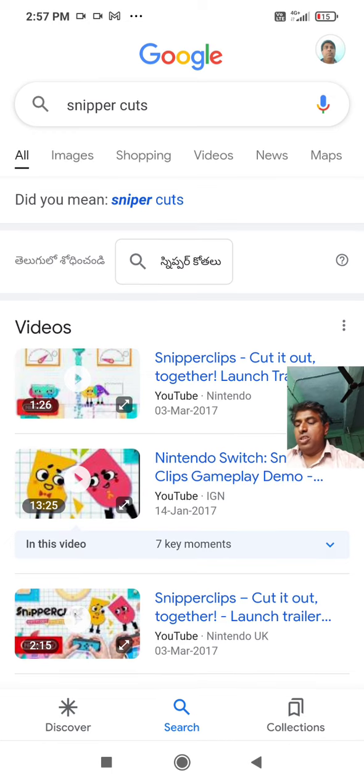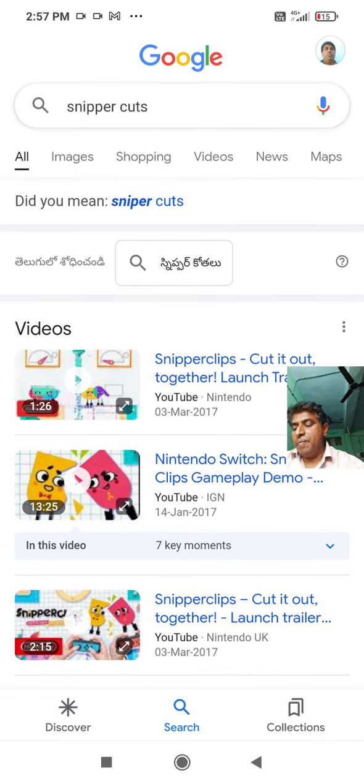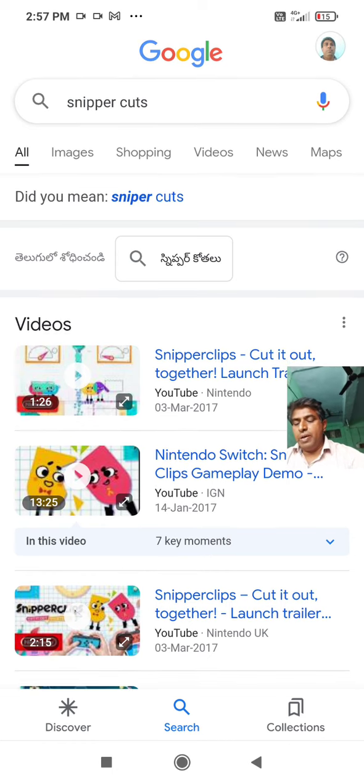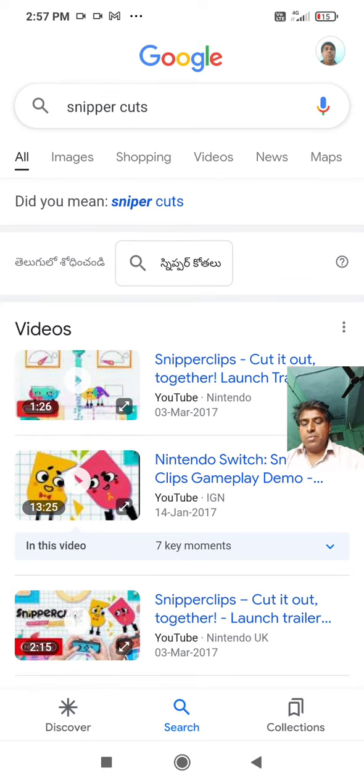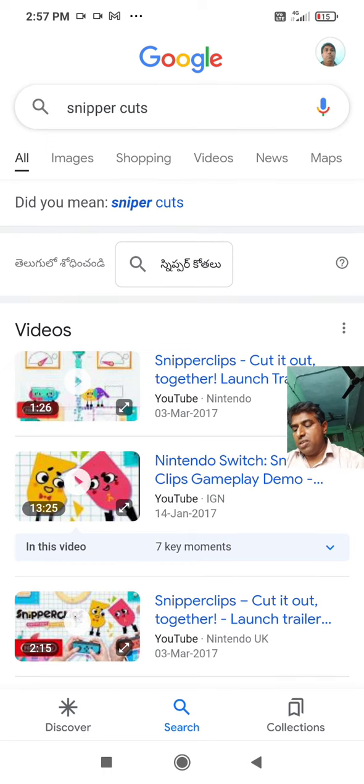So this is about the finishing operation, and now I will read: the quality of a pressing operation can be judged by inspecting garments for the following: burned or scorched garments, water spots, stains, gloss and or change in color, flattened nap or surface, broken zippers, buttons, etc. Creases not correctly formed, fabric of finished garment not smooth, wrinkle free and showing its proper appearance.